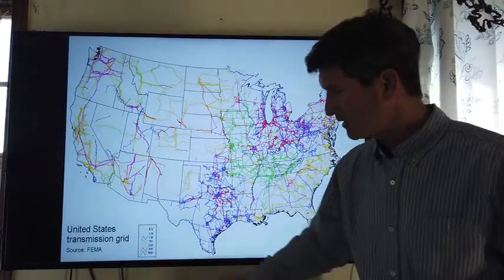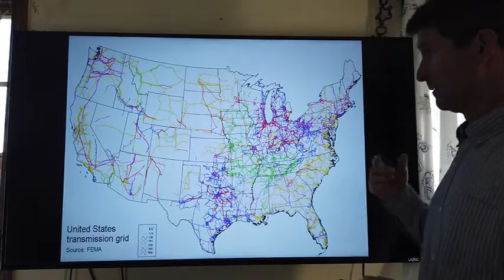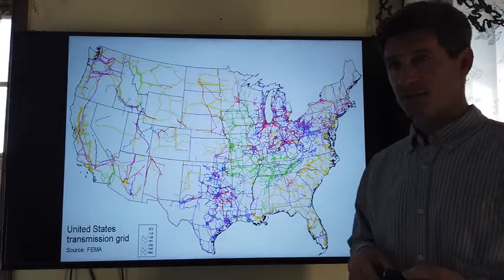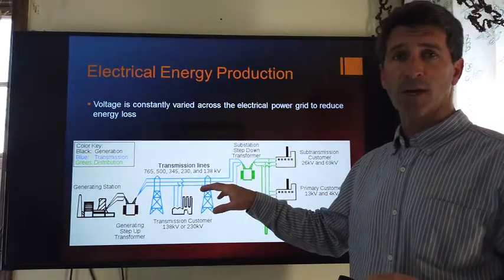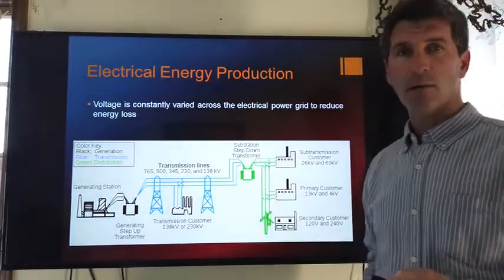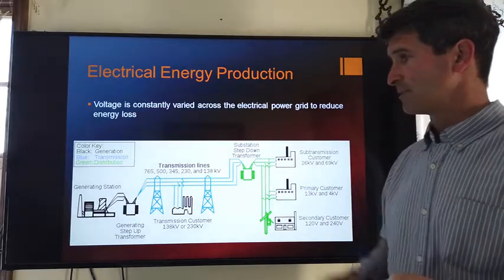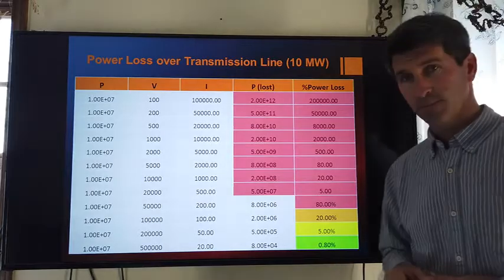The highest on this map is half a megavolt, but they are starting to put together megavolt DC transmission lines because, again, by making this voltage higher, the power lost just from heating up the lines, sending electricity through them, is much, much lower. If you're not convinced, let's do a little calculation.